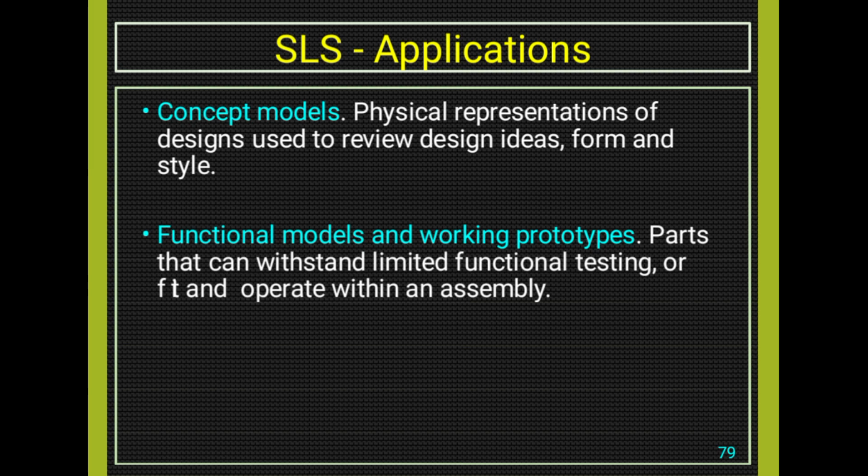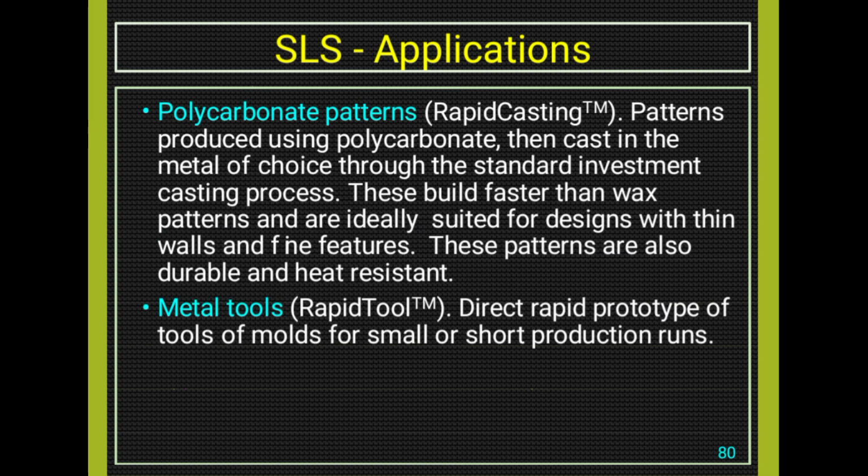Concept models, models and working prototypes. Next, the applications of SLS process can be also used as polycarbonate patterns in rapid casting, in metal tools as rapid tools, direct rapid prototype of tools for molds for small or short production runs.